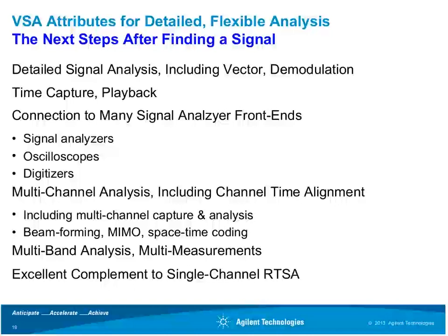I'm talking a little bit here about vector signal analyzers as the complement to real-time analyzers, with real-time analyzers being exceptionally good at signal or signal behavior discovery. That is, finding signals or finding signal behavior. Once you've found that with the real-time analyzer, the vector signal analyzer, often operating on the same analysis platform, then allows for much more detailed analysis in terms of things like time domain, demodulation, analog or digital demodulation, and, as I mentioned earlier, things like time capture and playback. This vector signal analyzer approach can be implemented in many different types of signal analyzer front ends, though I think most of the time RF engineers will be using spectrum or signal analyzers. This can also be applied to multi-channel analysis, but we won't get a chance to talk very much about that today.